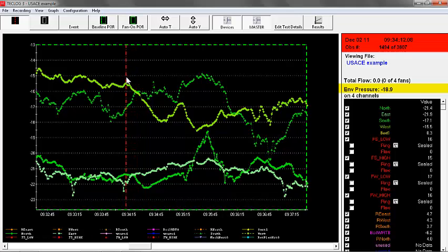We're staying pretty close to 19, within just a couple of tenths of a pascal of 19 for most of these data points as we move across the scale. So even though we have a wide variation in pressures on each side, the average of those 4 stays pretty consistent. So we get much better data if we're averaging on 4 sides of the building.